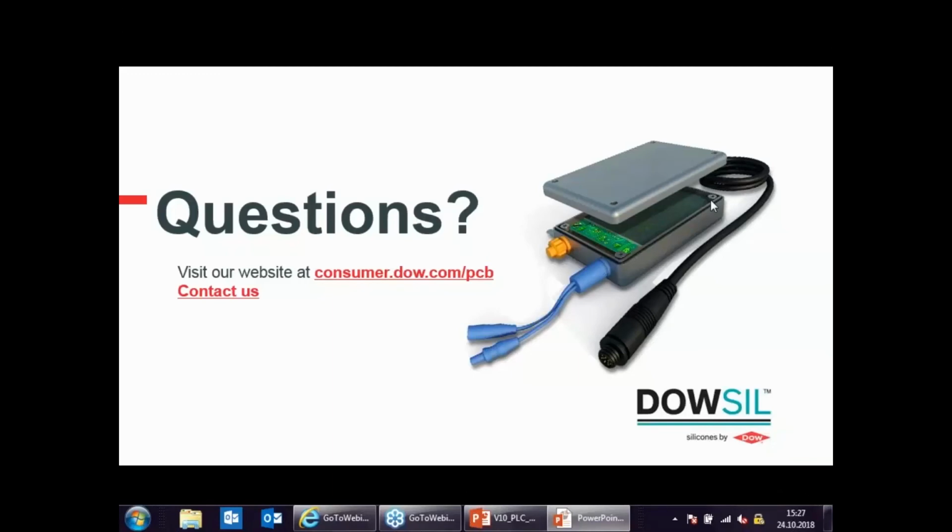So do you have information on outgassing volatiles from materials post-curing? So depending on the grade of the material, we have certain materials with what we call CV or controlled volatile material, where we have a limited amount of outgassing of volatiles. This is always depending on the technology behind.